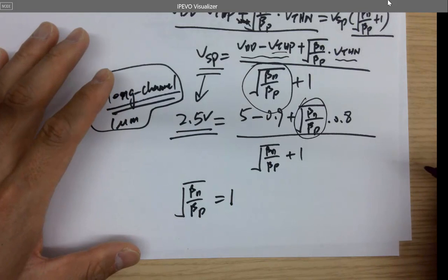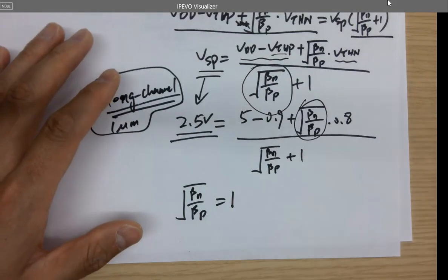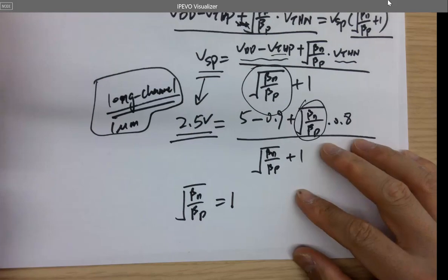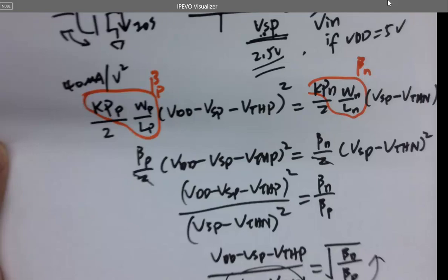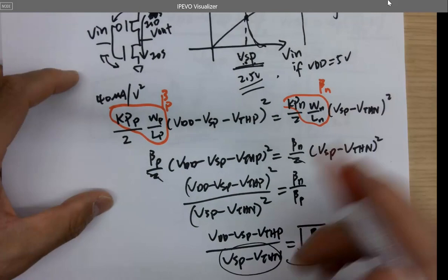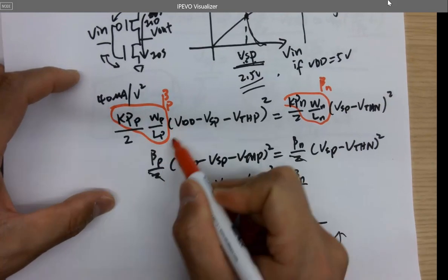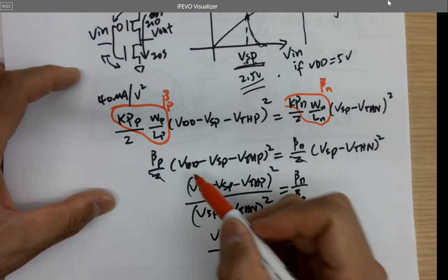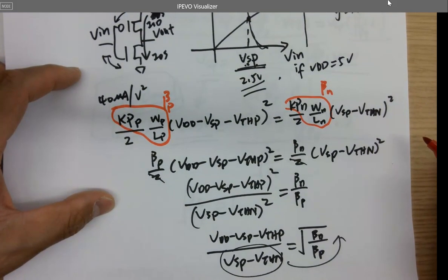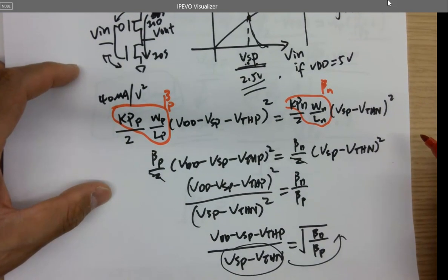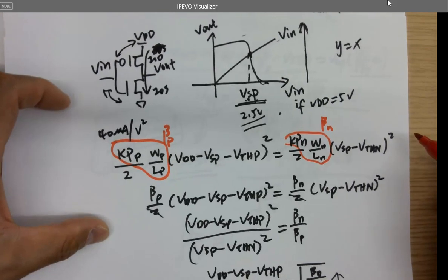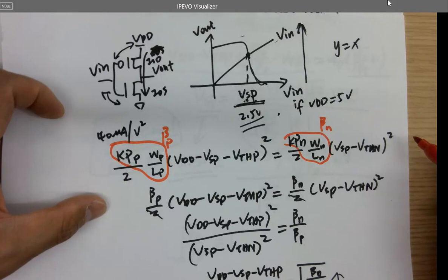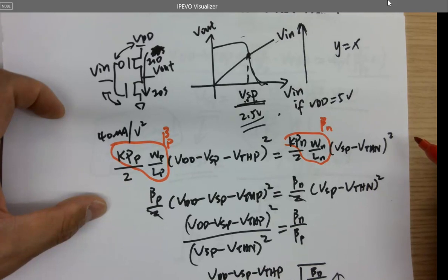Interesting? So if you want to design a CMOS logic gate and make a switching point in the middle, and you want these constants, the value here and value here, to be equal for the PMOS and NMOS, does that mean that you want to have the same width and length for the PMOS and NMOS?